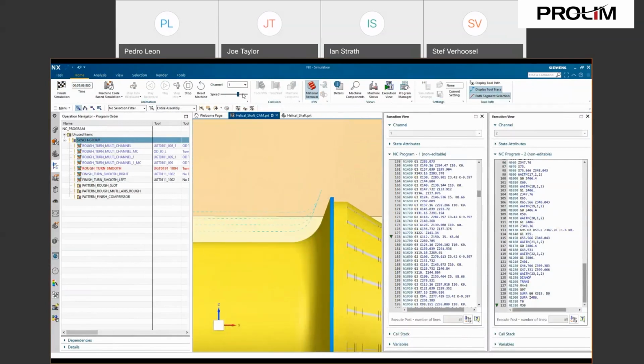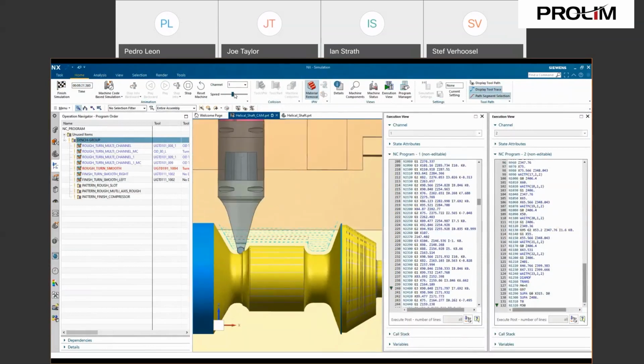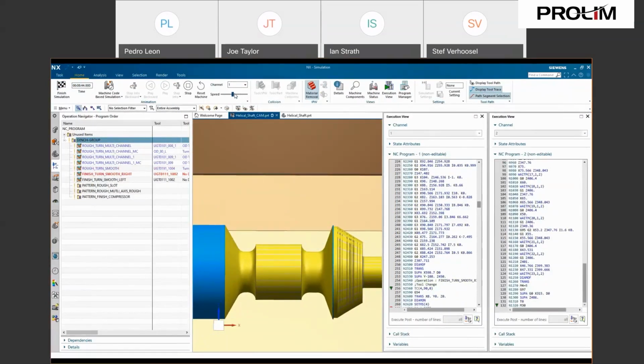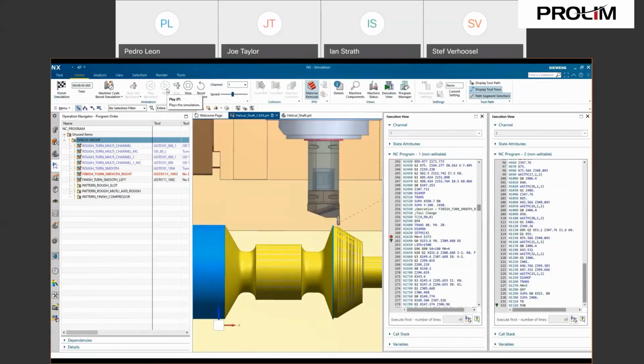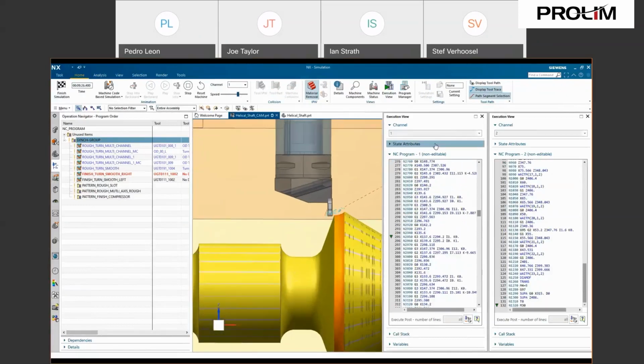difficult to machine materials, where there's wear on the inserts, maybe if it's a nickel alloy with surface hardening, which causes chips and notches in the insert. Being able to use this style of toolpath really spreads the load and the wear over the tool to give us better material removal rates.